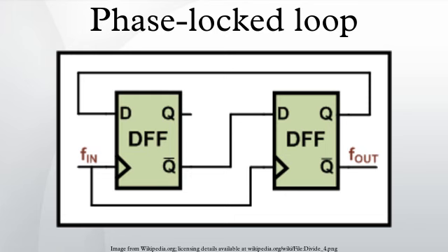The loop characteristics can be controlled by inserting different types of loop filters. The simplest filter is a one-pole RC circuit. The loop transfer function in this case is. The loop response becomes. This is the form of a classic harmonic oscillator. The denominator can be related to that of a second-order system, where ζ is the damping factor and ωn is the natural frequency of the loop, for the one-pole RC filter.